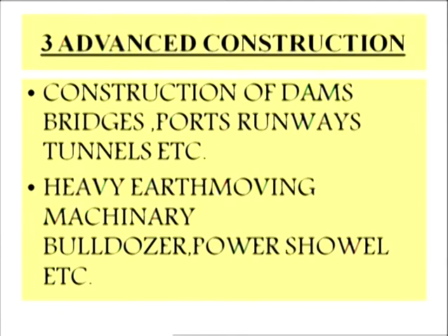There are different types of the foundations. These foundations for the bridges are the pile foundation and the well foundation. These are the foundations normally constructed for the construction of the bridges. Cofferdams and caissons are required to be constructed for the underwater foundation. So this advanced type of the technology is required in the case of construction of these heavy structures.